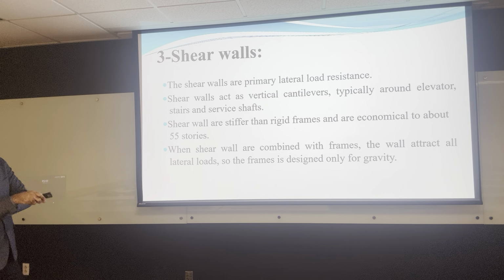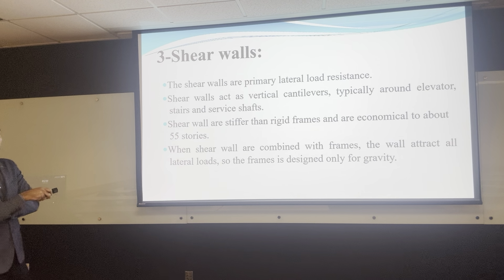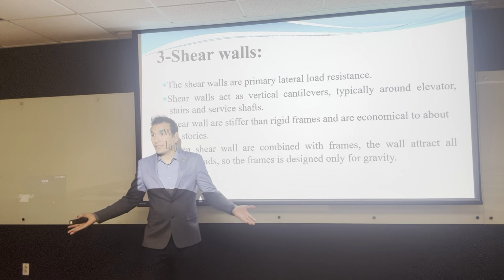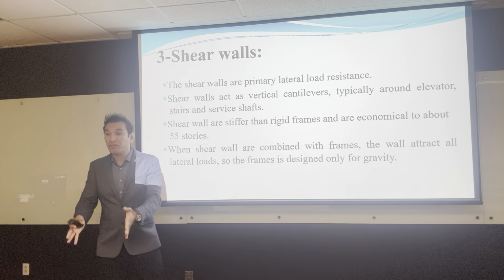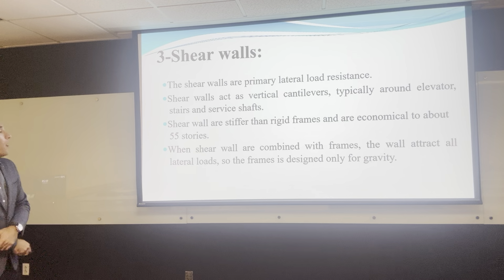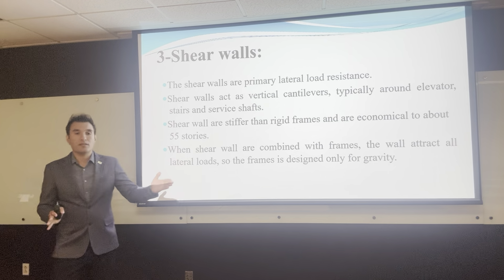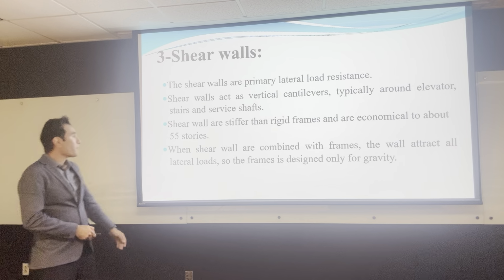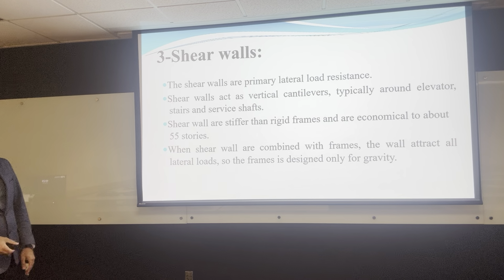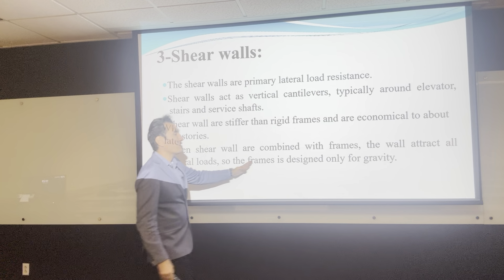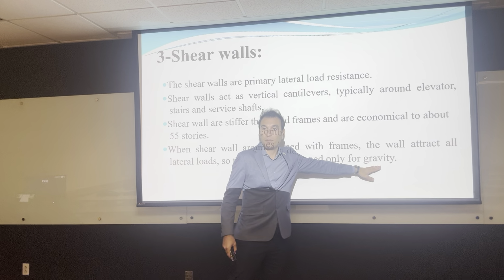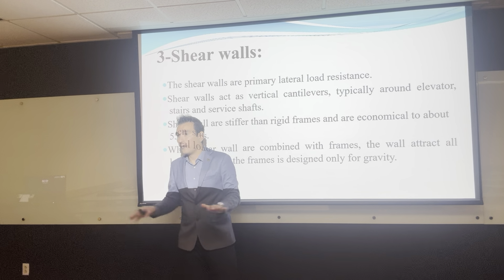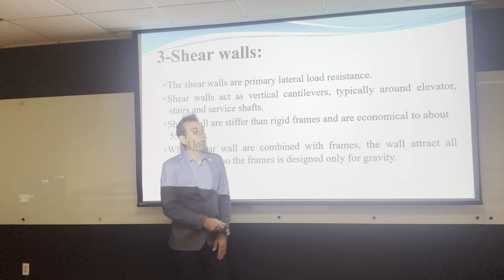And shear walls are a very good and economical system up to 55 stories. However, we use them up to like 90 stories or 100 stories because they are the best systems. Even though it's going to cost more, it's the best system. And why? Because sometimes other systems that are cost effective can't be used because of architectural restraints, okay? All right, when shear walls are combined with frames, the walls attract all the lateral loads and the frame is designed only for gravity. That's what happens. If you have shear walls, we design so that all the lateral loads are absorbed by the shear walls and the frames, columns only take the gravity loads.